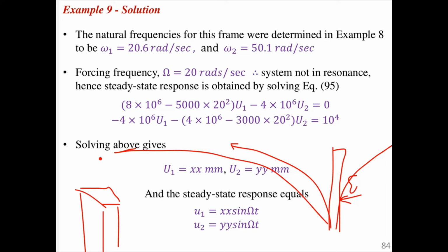The failure of structure can be what you call structural damage or aesthetic. In engineering terms, we talk of ultimate limit state and serviceability limit state. For example, why we check a structure against SLS, we design for SLS serviceability is like you have a building or a roof made of timber joist. You don't want a deflection occurring that is so unsightly or so inconveniencing, such that the deflection that occurs can make your doors and windows not to close. If you have used a beam or a lintel, and that lintel you have just used the timber joist, so you don't want the deflection.